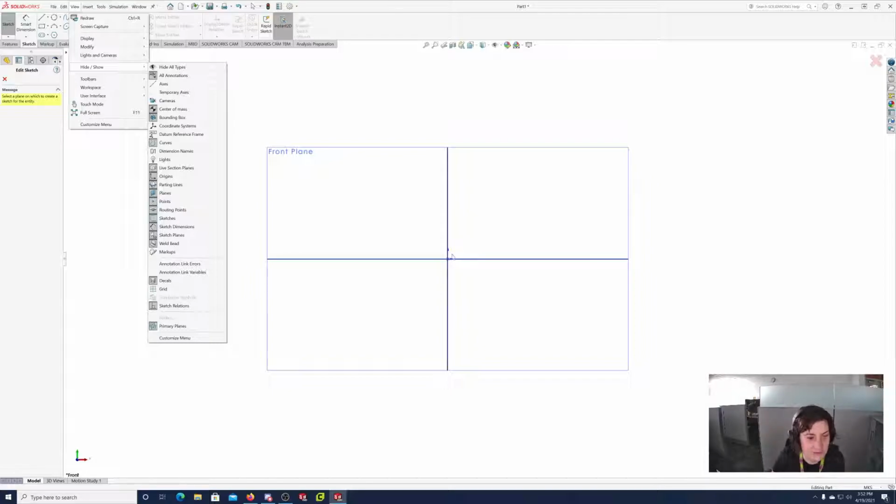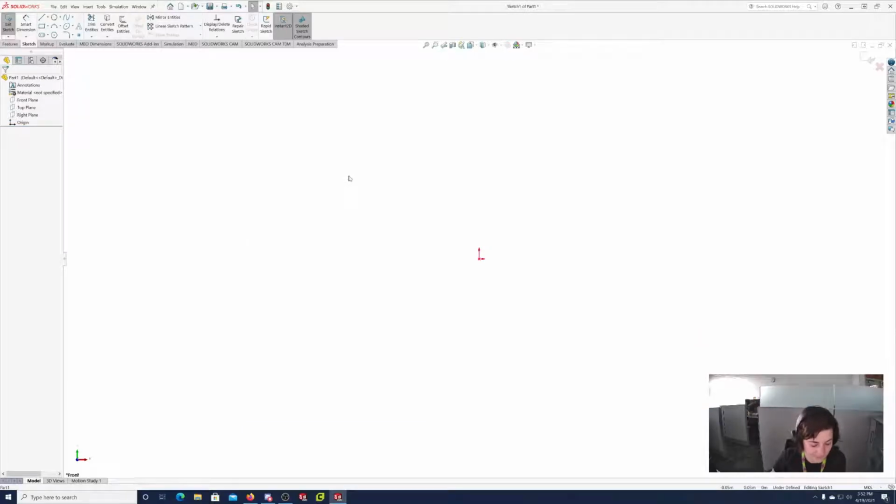So yeah. All right. So we're going to select the front plane at this point, if we haven't already. We're on page 3-6. So select the front plane from the feature manager tree. And we already actually did the start a new sketch command. I'm just making sure we haven't already done stuff. Okay, so now we're going to select the line command up here.